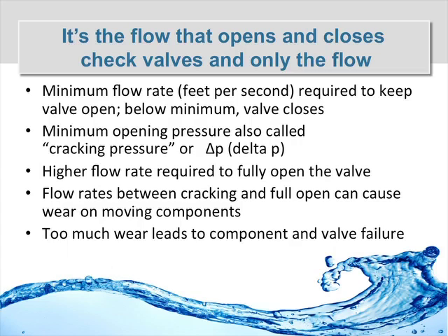Higher flow rates are required to fully open the valve than the cracking pressure, so you've got to think about whether this valve will just be off the seat, or will it be fully open? And that's, again, the result of calculations. Flow rates that are in between cracking and the full open position can cause wear on the moving components of the valve, and of course, eventually wear is going to lead to component and valve failure.